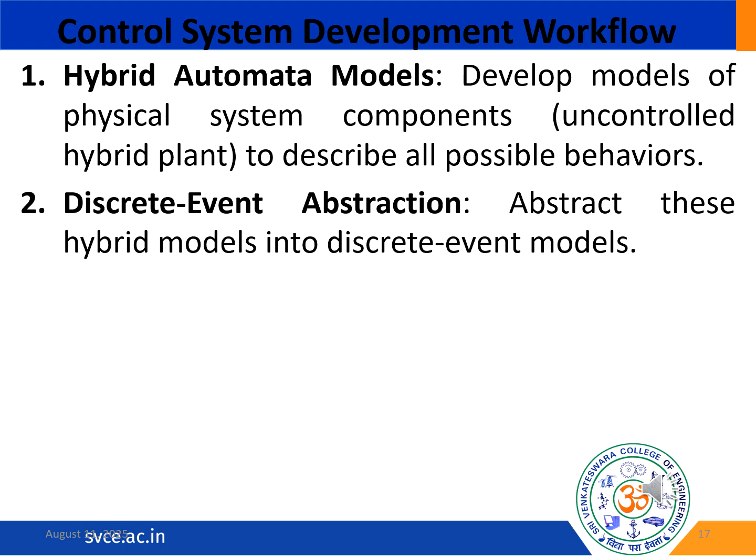So this creates a discrete event model of the uncontrolled system. This means that the hybrid plant, which has been introduced above with all these particular descriptions, has been abstracted into a discrete event model. This is achieved by removing all continuous variables. So all these declarations are removed, and the differential equations in which their evolution over time is defined are also removed.